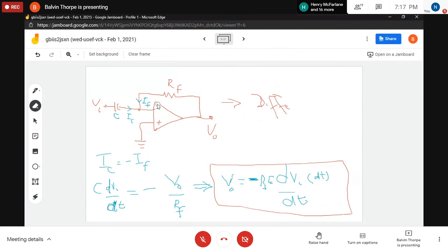If you're talking about the calculation, we'll have plenty of that next time. For this circuit, the output voltage has to be minus RF, which you're going to guess as a value, times C. You're going to realize something soon, and you should probably realize it again from network, but I'm not assuming anything. Any time you have R times C, whatever R is, that's really a time constant. So it's going to be RF times C, times the differential, or differentiating, the input voltage with respect to time.